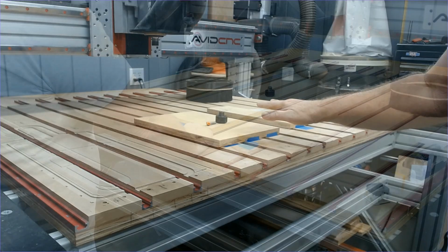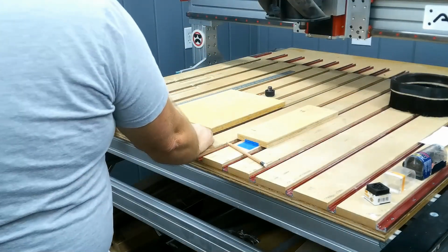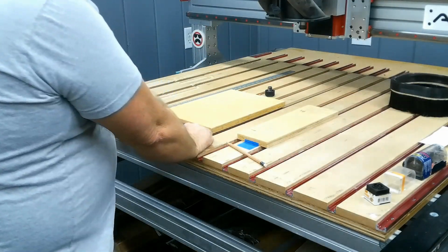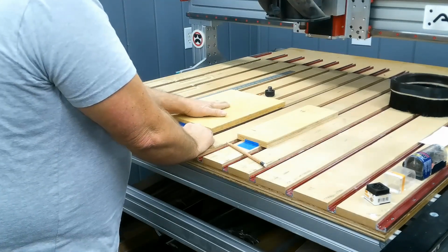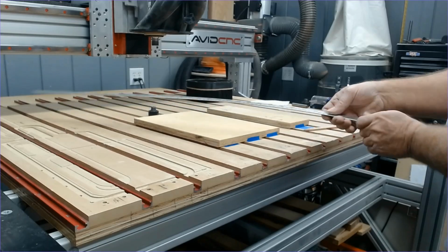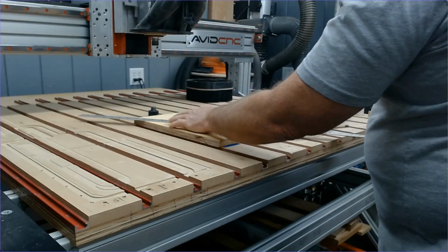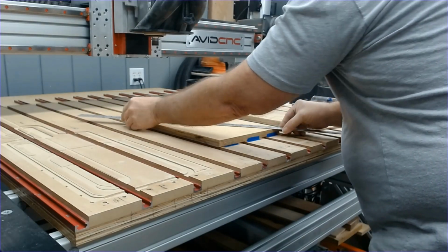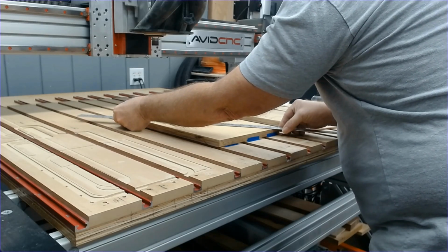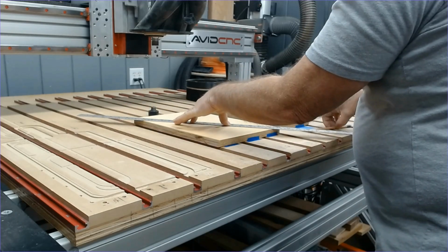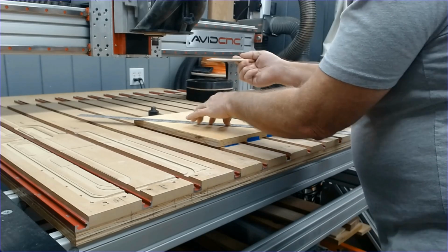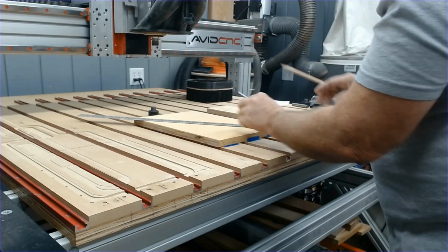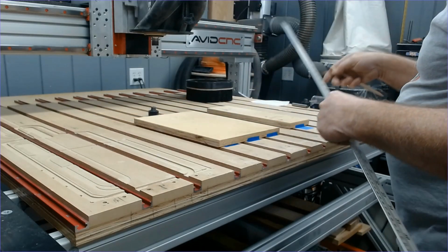your CNC router. Okay, for our first sheet that we created, which was XY datum position in the center of the material, all I'm going to do is take a straight edge and I'm going to line it up on the corners of said material, and I'm going to come over here somewhere close to the center with a very sharp tip on my pencil. I'm going to strike a line.